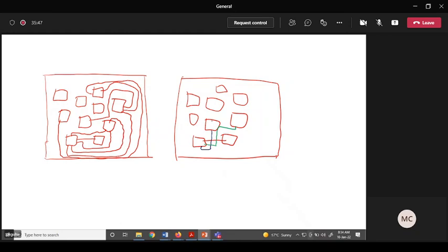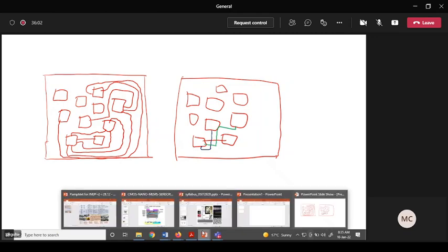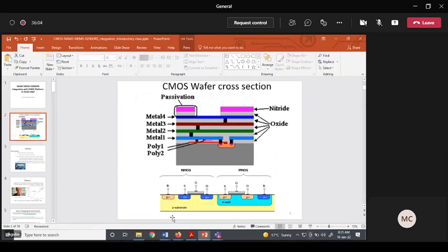Okay, so within a very small footprint I will be able to connect them, which is very difficult if I only have one metal line. That is why we are basically using the third dimension to reduce the footprint. So that is why we need several metal layers.